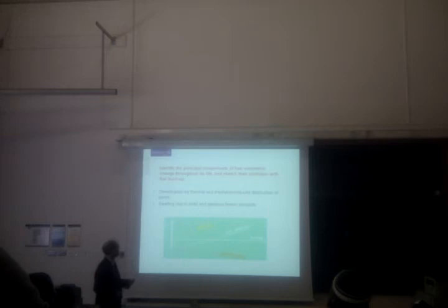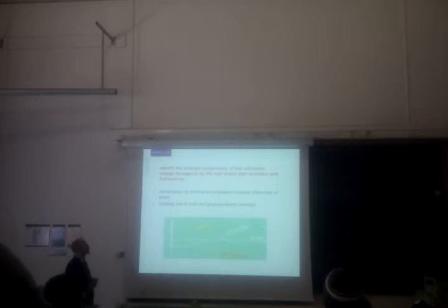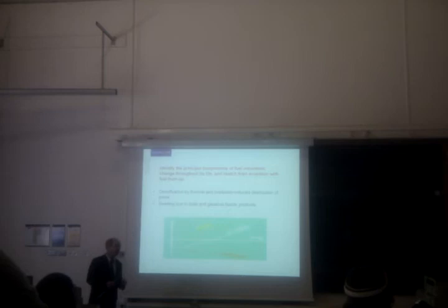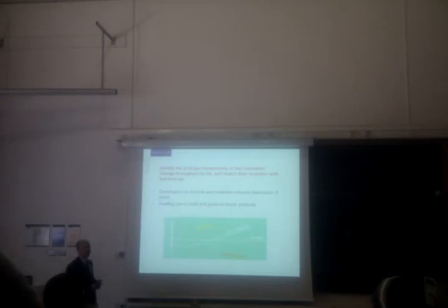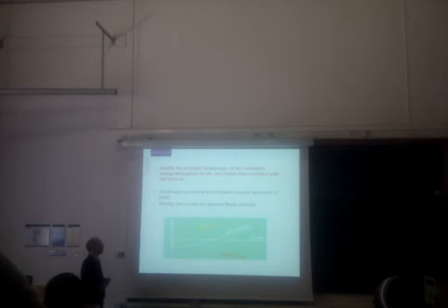What about the volumetric change of fuel pellet when we put it into the reactor? You may remember, but if you don't, you can look at the diagram, that there are 2 major components to the volumetric change in the fuel as it goes throughout its life, as burnup increases. One is due to the fact that every time we undergo fission, we're replacing a single uranium atom with at least 2 different fission products.